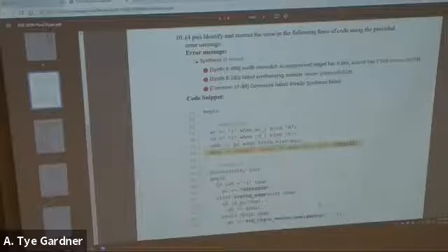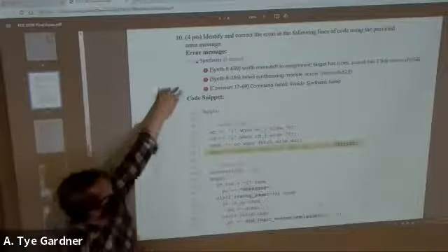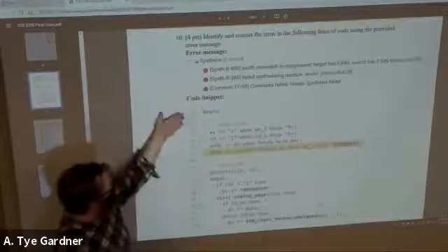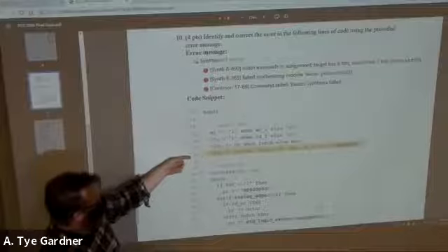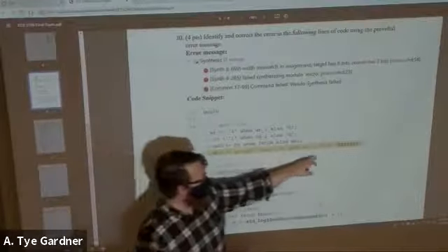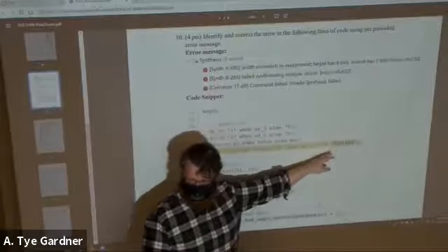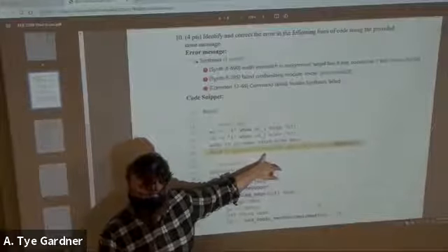Take just a minute to look at this and see if you can find the error. There's only one. This one's easy. Just put an extra Z in there. Yes, exactly. So the hint, right, is that it's in line 58. There's also a line that says 22, but there's no line 22 in this code, so that's kind of not helpful. Line 58, you come down to here. It says, well, data is assigned to this. I'm missing the Z here. There's 7 Z's, and this is 7 down to 0, which means 8 bits, right?